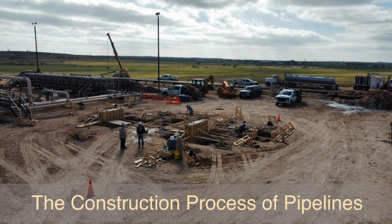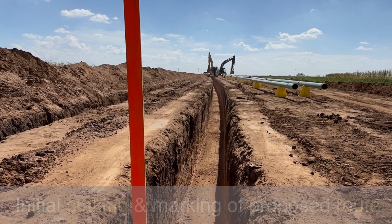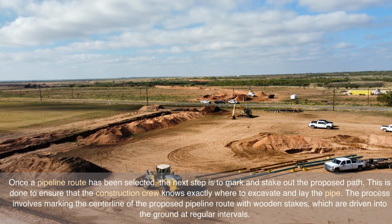The construction process of pipelines. Initial staking and marking of proposed route. Once a pipeline route has been selected, the next step is to mark and stake out the proposed path. This is done to ensure that the construction crew knows exactly where to excavate and lay the pipe. The process involves marking the center line of the proposed pipeline route with wooden stakes, which are driven into the ground at regular intervals.